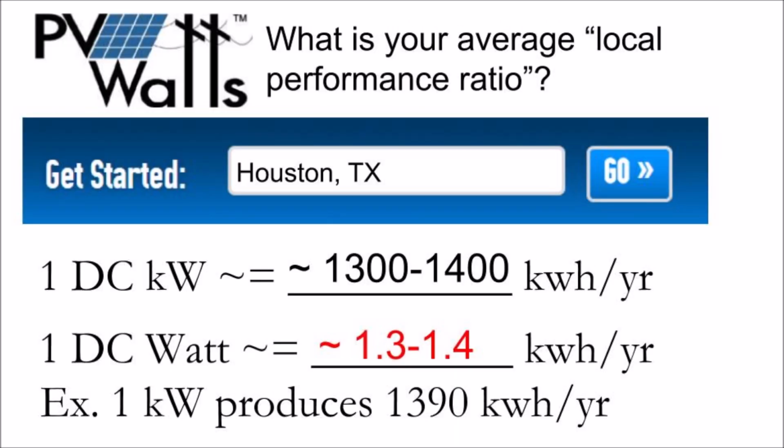If I know for my area, 1 kilowatt of rooftop solar will produce roughly 1,400 kilowatt hours per year, then 1 watt of solar will produce 1.4 kilowatt hours per year. That figure might be discounted 10 to 20% if the tilt angle is atypical, but for the most part, these calculations can be performed mentally in conversation to be later confirmed with a three-dimensional computer model and full shade analysis.